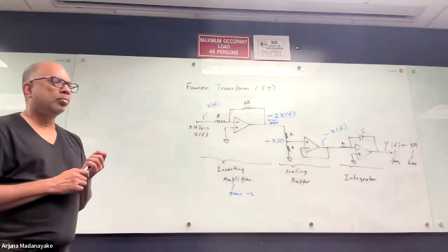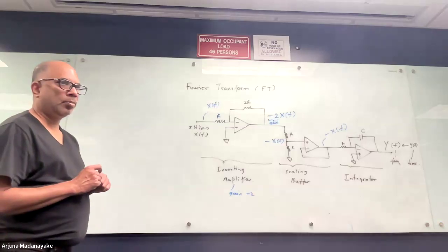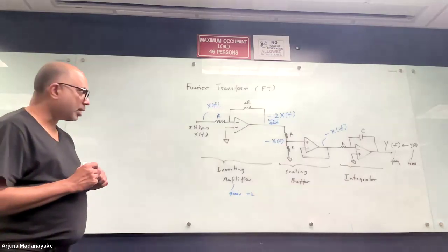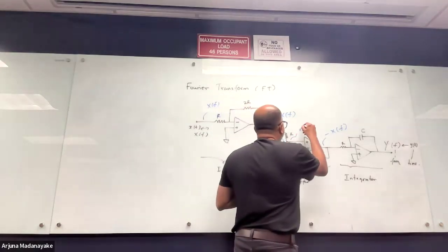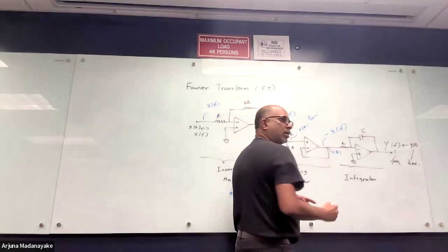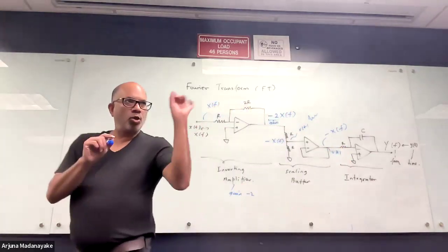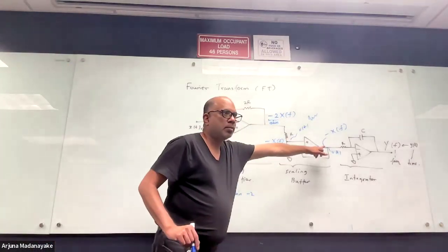Voltage divider, I understand the voltage divider part, but when it goes to the buffer, isn't it a non-inverting op amp? It is. So whatever the voltage here, let's say the voltage waveform is V of t, some waveform, is still the same here. It doesn't change. So it just looks at the divider point here and applies it over here without change.